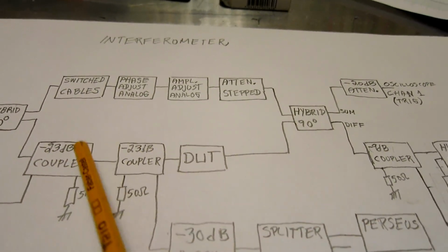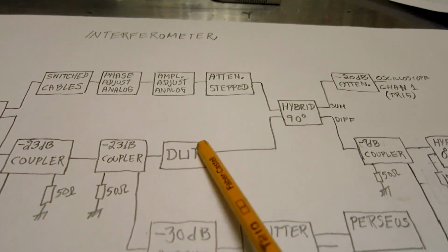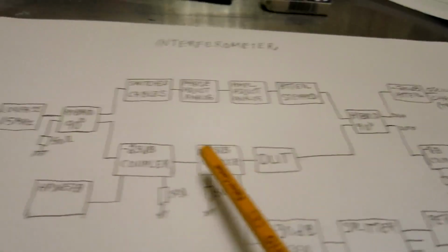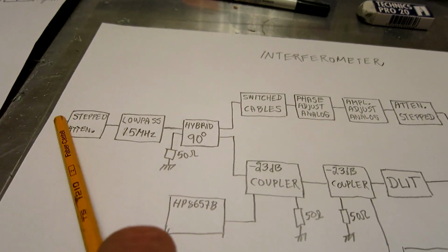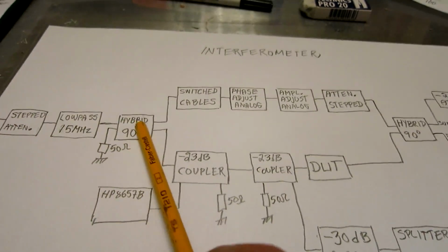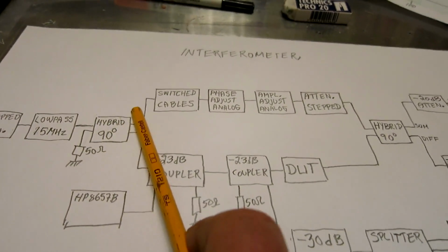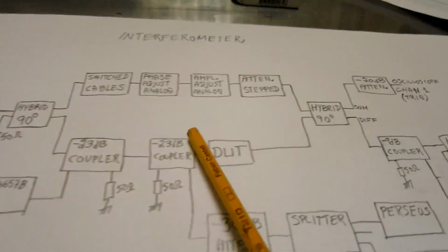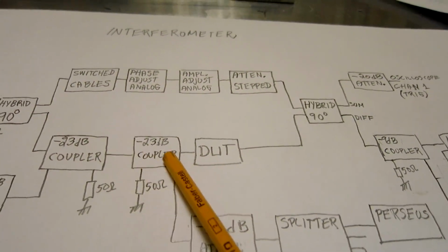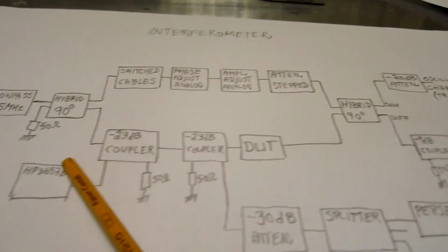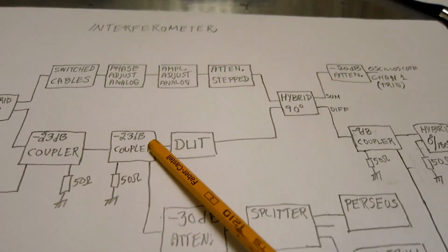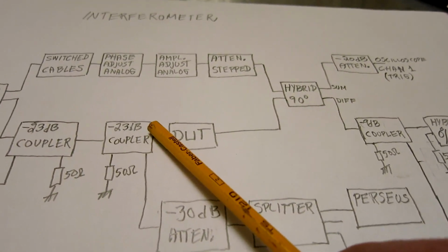It means the signal that goes through the device under test and that comes from the signal source, the local oscillator, the Wenzel here, which is split into 2 equal parts. And it also picks up whatever I have sent into this leg with this signal generator. This is for calibration purposes.